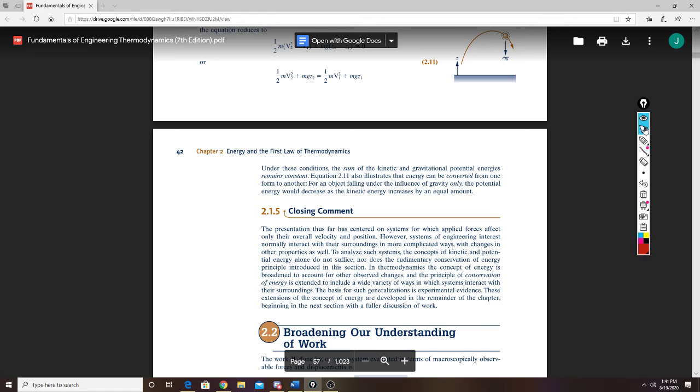And then there's another one called the law of conservation of mass. What that one means is pretty simple. Let's say that this right here is a water faucet or something, or a simple heat exchanger. If you have 1 kilogram going this way, and then you have 2 kilograms coming down here, the exit, their addition has to be equal to 3 kilograms, right? So conservation of mass means that mass is not leaving this system in any way. It's conserved. So that's what that one is, and they'll talk about that one in a minute.